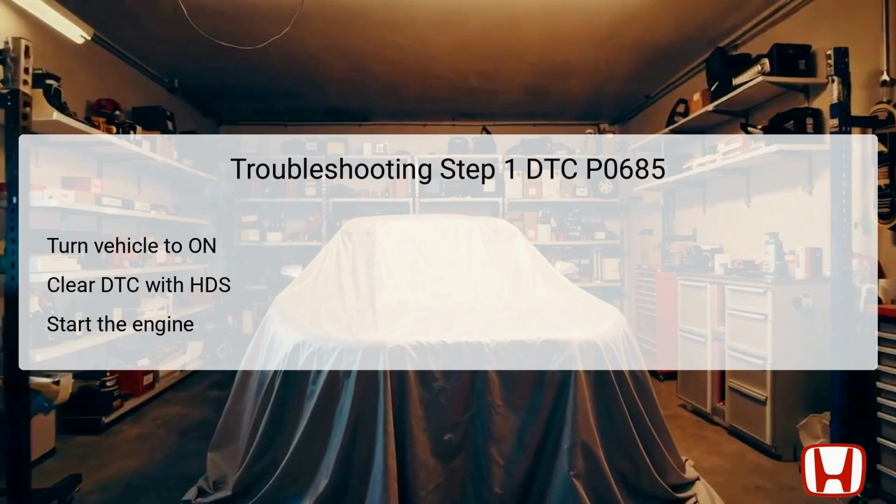After clearing the DTCs, start the engine. Following this, check for any pending or confirmed DTCs with the HDS once more. If DTC P0685 is indicated, it confirms the failure and mandates further steps in the troubleshooting process.